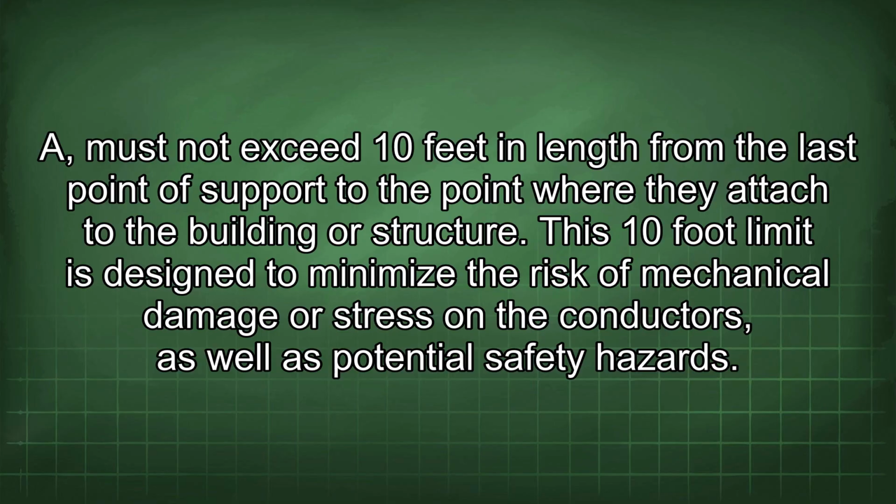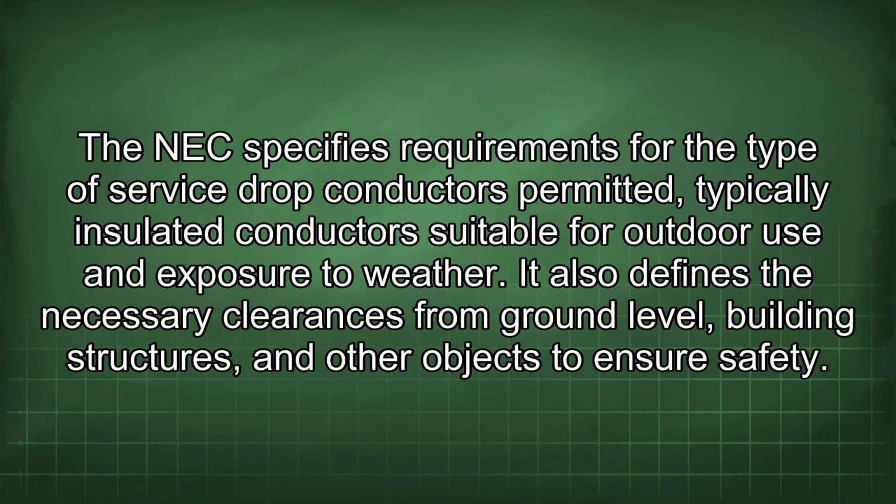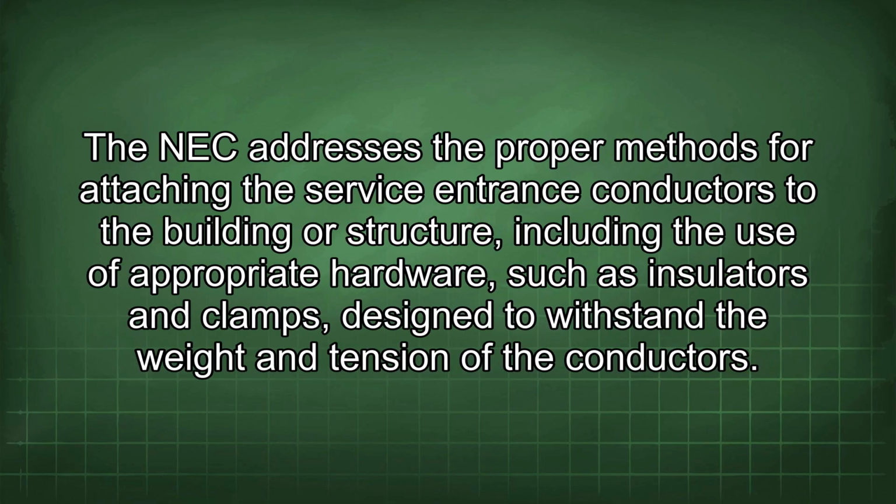potential safety hazards. The NEC specifies requirements for the type of service drop conductors permitted, typically insulated conductors suitable for outdoor use and exposure to weather. It also defines the necessary clearances from ground level, building structures, and other objects to ensure safety. The NEC addresses the proper methods for attaching the service entrance conductors to the building or structure, including the use of appropriate hardware, such as insulators and clamps, designed to withstand the weight and tension of the conductors.